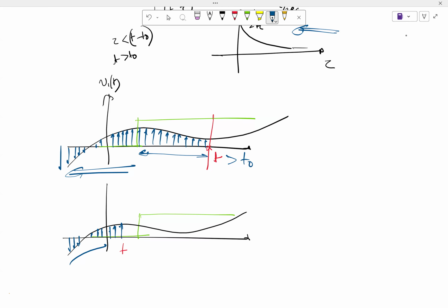And when we talk about the sinusoidal steady-state response, in an LTI system that is equivalent to asking what the response is to an input that is a complex exponential, e power j omega t.